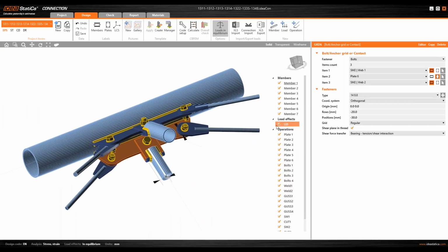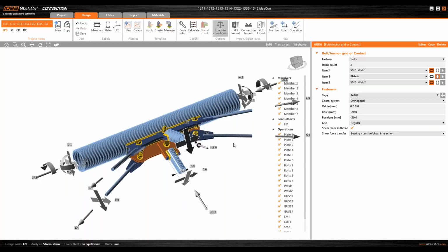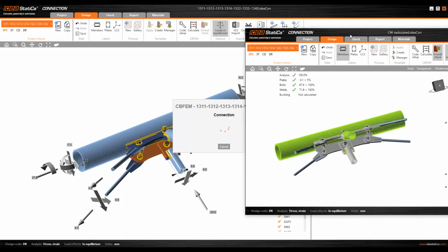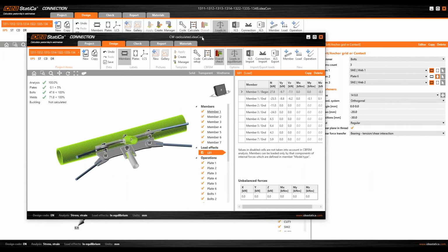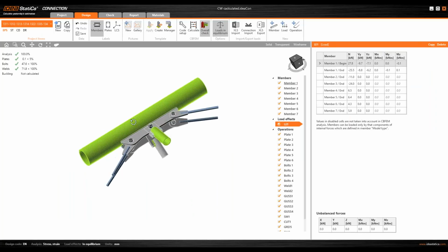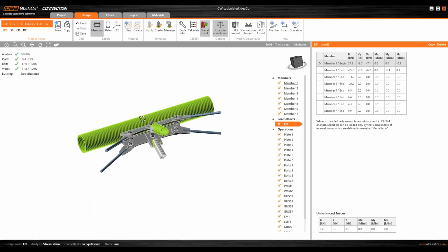So now we finished the design. I can turn on the forces and calculate. Now a minute or half a minute. Well, I can cut this time. I have it calculated here in an extra file. So let's see about the results. All is fine, green, gray. We passed the code checks. Design is quite okay. Everything well calculated.